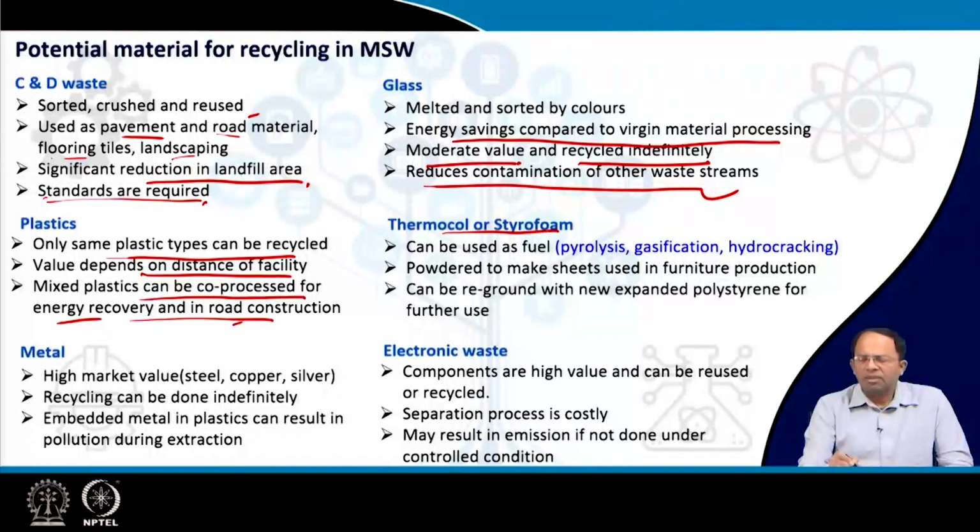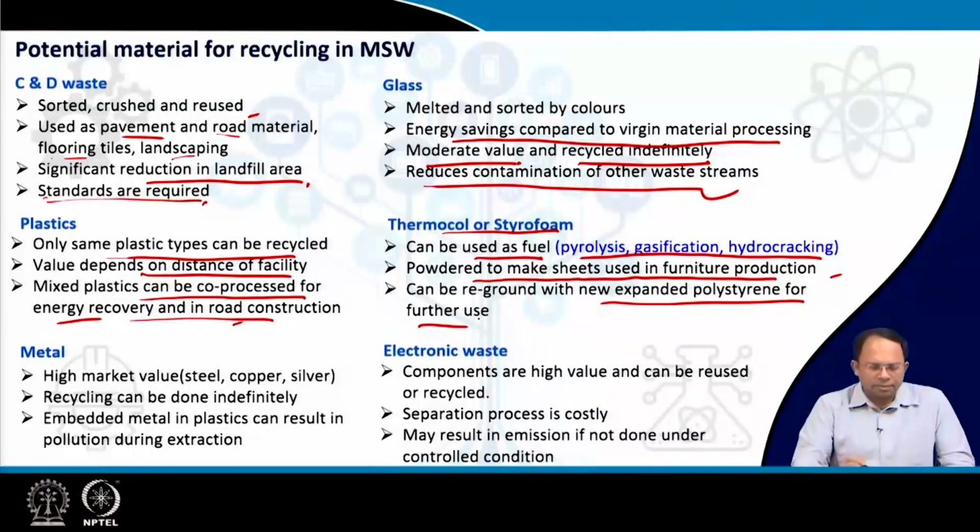Then thermocol or styrofoam, not everything can be recycled, particularly used ones. Fully soiled and used ones are difficult, but could be used for burning, like pyrolysis, gasification, hydrocracking. These are different incineration processes. There we can use it as a fuel, but we cannot recycle it directly. It could be powdered to make sheets used in furniture production. So this is one form of recycling, you can say. Can be reground with new expanded polystyrene for further use to a certain extent.